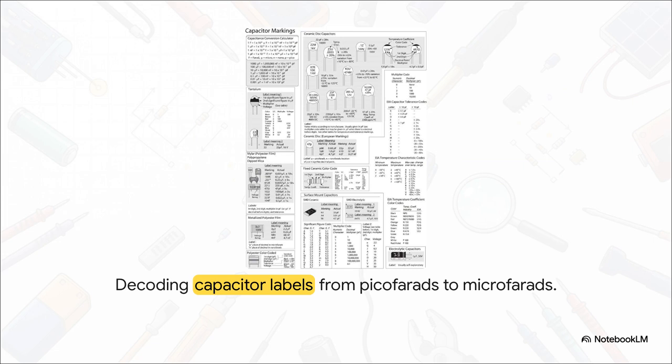And the cool thing is, this brilliantly illustrates how capacitors have their own similar yet totally distinct labeling systems. For instance, ceramic disc capacitors use a marking system that usually gives values in picofarads along with specific letters that indicate their tolerance range and how they're going to behave when temperatures fluctuate. Again, it is all about incredibly compact communication.